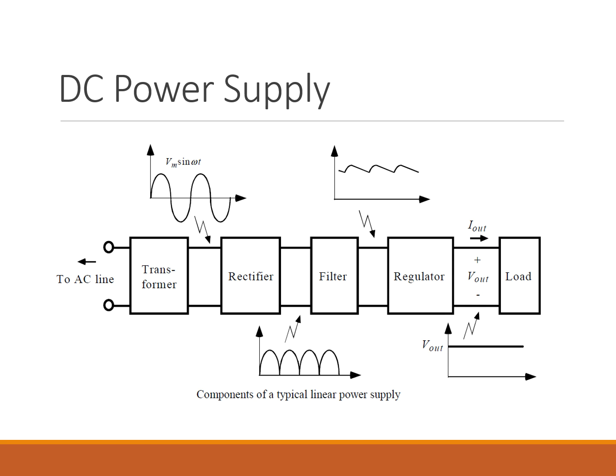So to recap, waveform evolution: we start off with AC in, which is sinusoidal. It's rectified, which looks like pulsed DC. Then we filter it, which looks like smoother DC, but with still some ripple. And then we regulate it, which looks more like a flat line, steady voltage. Right? And that's how you go from the wall socket to, let's say, your USB port.